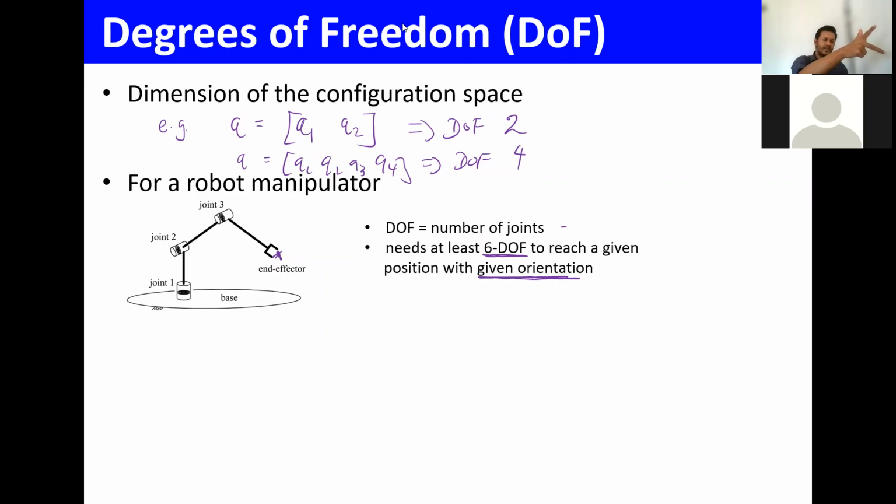For approach, we can actually do it with 3 joints, because for a 3D position, X, Y, Z, if we can control that, then only 3 joints are needed to go to a certain point. But let's say we need to have whatever orientation. This is like a coordinate frame I'm showing here, so we not only go there, but have a different orientation.